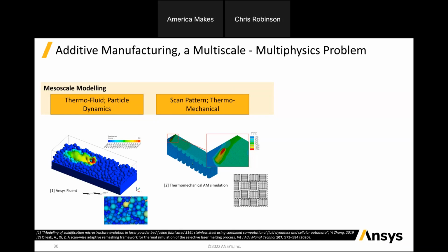And what we're looking at here is specifically laser powder bed fusion, where you can take into consideration individual build files from specific machines, or generic build files. With the DED process, you can also follow the G code and trace out the thermomechanical solution, going through that thermomechanical solution based on what's going to happen in your specific part build.